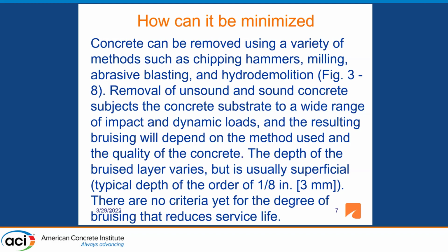And there's really no criteria for the degree of bruising and the impact of that degree on service life. Some overlays placed on bruised surfaces have lasted a long time, but it's difficult to quantify because it depends on so many factors: the loads on the overlay and the thermal stresses on the overlay and so forth. So if you need high bond strength, bruising is going to hurt you more. If you don't need much bond strength, bruising is less important.